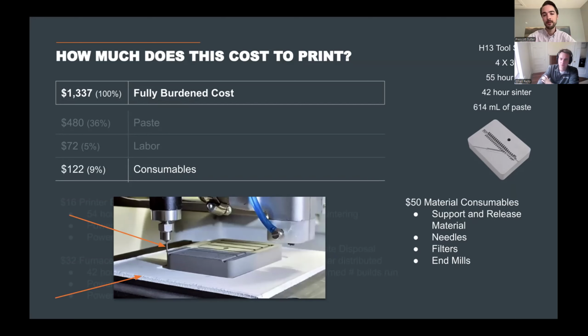Sure. Are those cutting tools custom to the Mantle process, or are those standard, or can you just elaborate a little bit more on the end mills? Yeah, great question. These are end mills which are available through a variety of traditional vendors. They're not specialty. A distinction here is they are all carbide coated, but otherwise they're run-of-the-mill subtractive tools that you would use on CNC machines, machining centers, and the like. Yeah, good question.